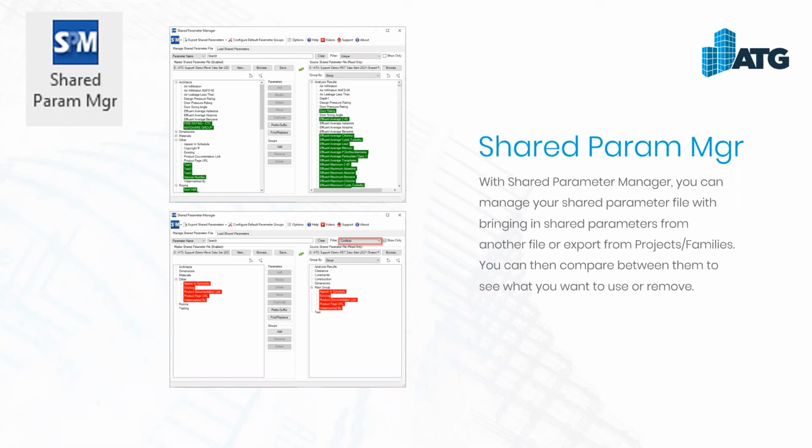So if you have a project you get from someone and you need a list of their shared parameter files or shared parameters that they have, you can use this tool to export those shared parameters out to a file. Then you can use the compare feature to compare what it was exported with your shared parameter file so that you can see if they are the same parameter or if they're different parameters and are not needed, or if you want to use yours and modify theirs.